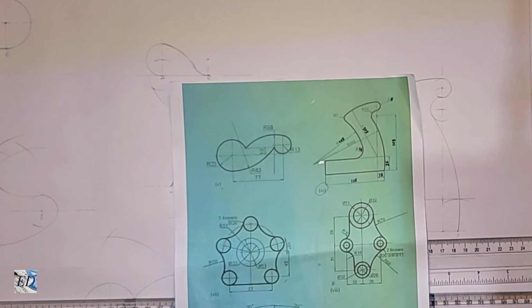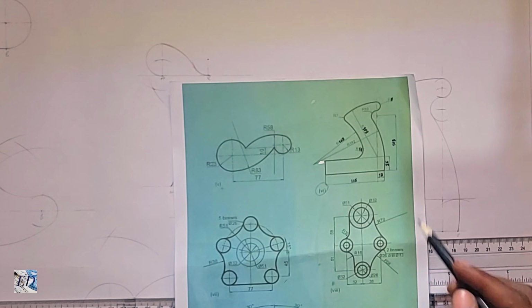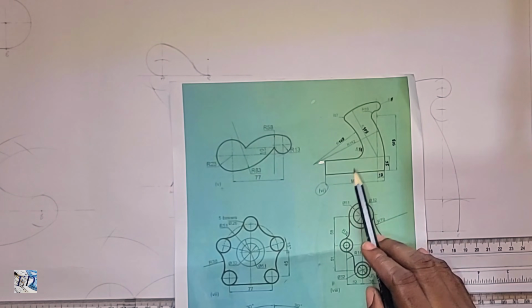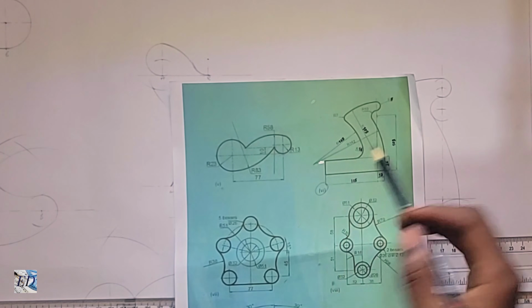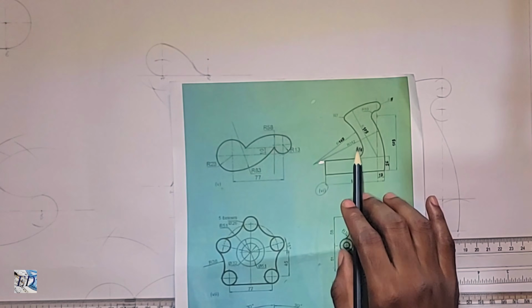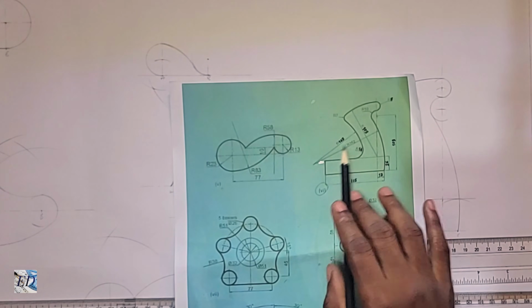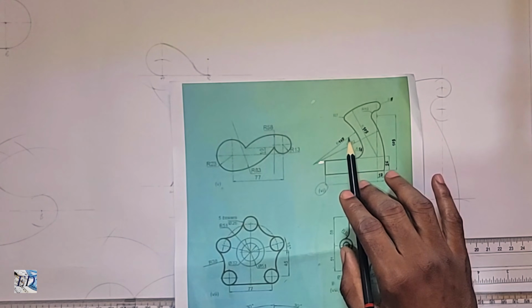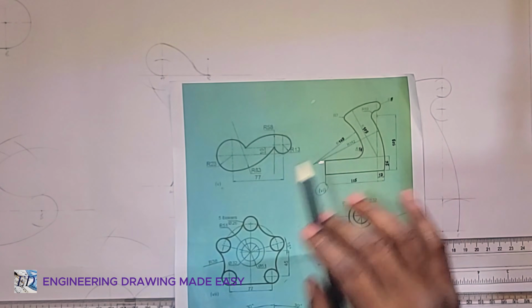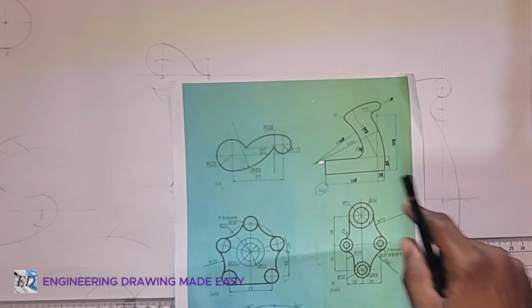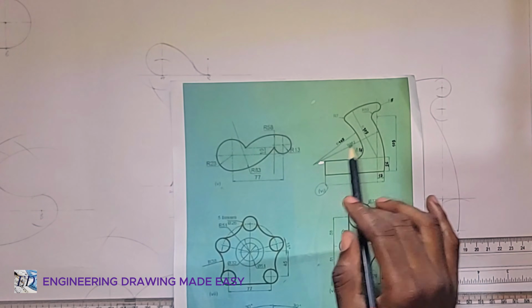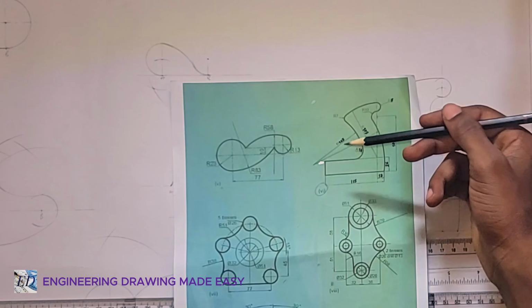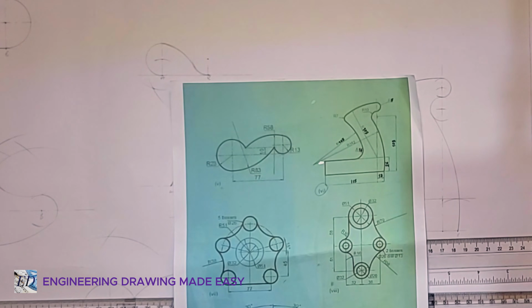The next thing would be this circle, right? And once again, if you take a look, it is touching this arc internally. So the distance here would be this radius 103 minus 16, and since it's touching this line at exactly one point, it should be at a distance from the line of 16.